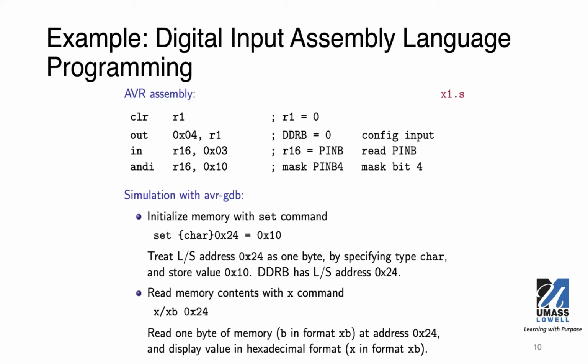If you write a C program like you did, you can use the Arduino libraries, built-in functions. But here we want to show you what happens underneath. So when your code sets the pin mode and reads the value from the port, underneath, this is what we'll have in terms of assembly language instructions.